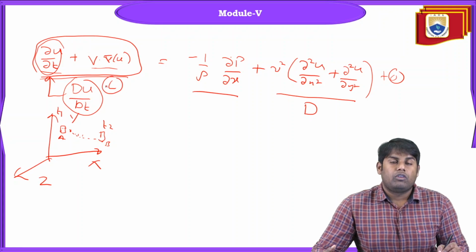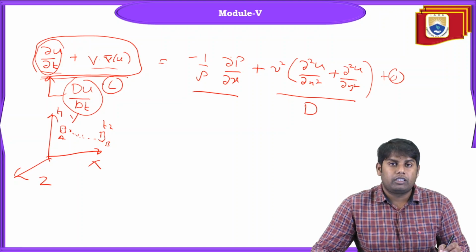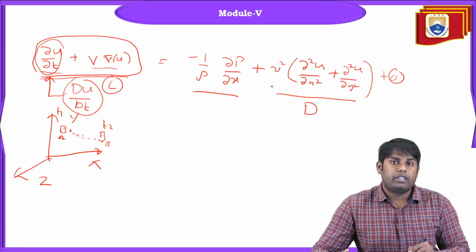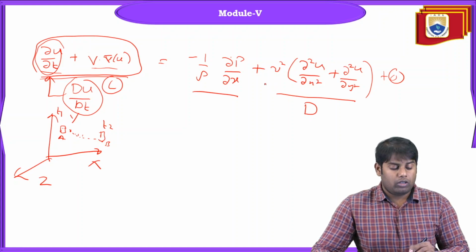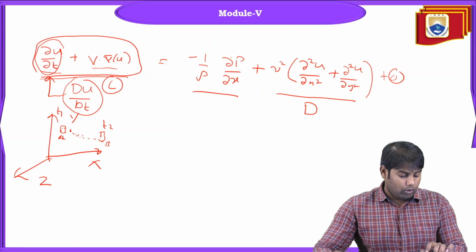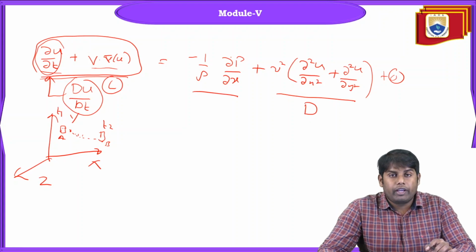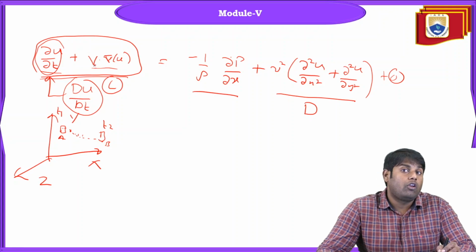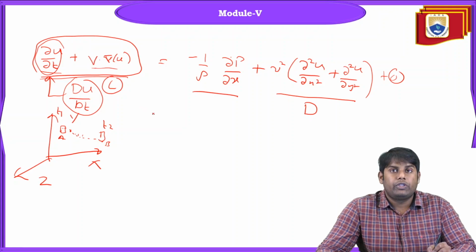When you are performing numerical analysis or numerical simulations, the convective term and the diffusion term, their combination has to be treated properly. Why? Because when you are integrating or combining both, you cannot use the same scheme for both. Why? Because the convection term is a non-linear term. Basically, if you see here, you have u into dou u by dou x, something like this.